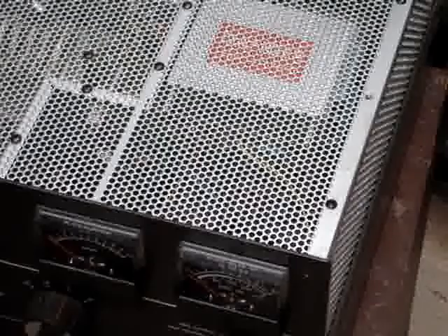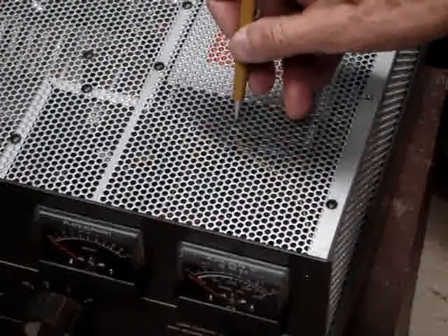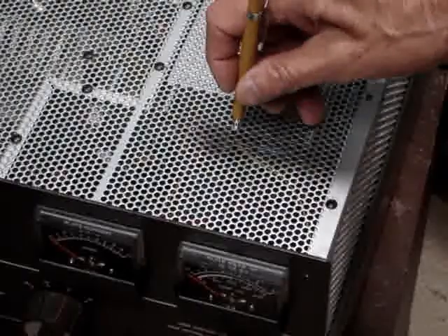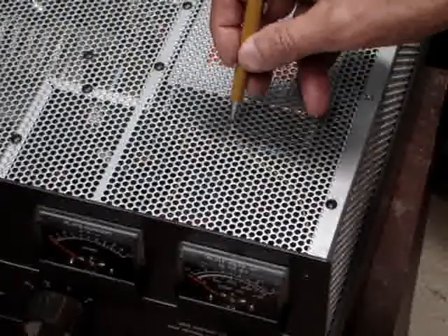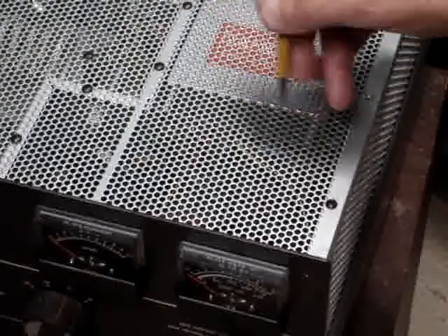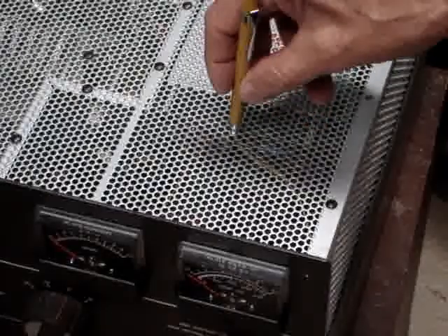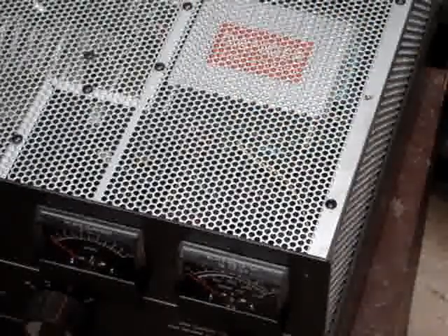okay, as I'm assembling the amplifier here, I wanted to point out on this particular amplifier, an SB220s, that the Zener diode is right under here. If I took this lid off, you can see it. It's right at the top of the board, so it's very easy to get to. And like I said, I just soldered a shorter wire across it there. So I just wanted to point out where you need to look for that Zener diode that we're bypassing.